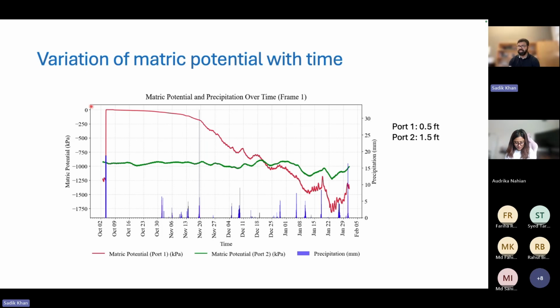So if you look into the data, due to the rainfall simulation, the matric suction drops significantly, it becomes close to zero, and then over a period of time, whatever the pull of the moisture, the matric suction goes up pretty high. When the matric suction goes up pretty high, the shear strength goes up higher. So the gain in the factor of safety is much higher in this case because we are utilizing the evapotranspiration action of the slope.